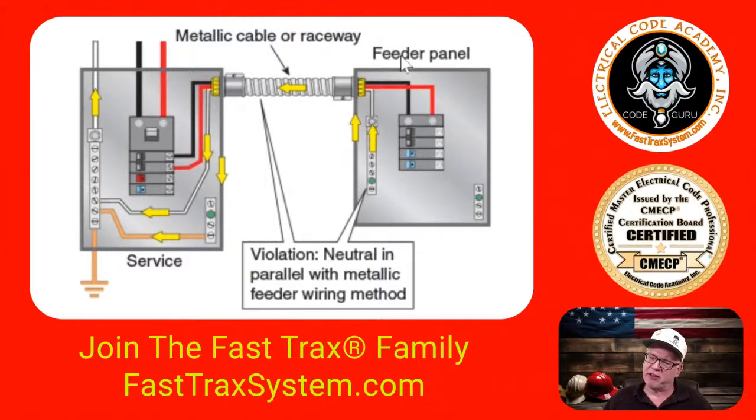So some people say, so this is a violation. Now, what does this violate? What code rule does this violate? Objectionable current, obviously 250.6. We're creating objectionable currents. We're creating issues as a result of objectionable currents, which can cause problems with sensitive electronic equipment.